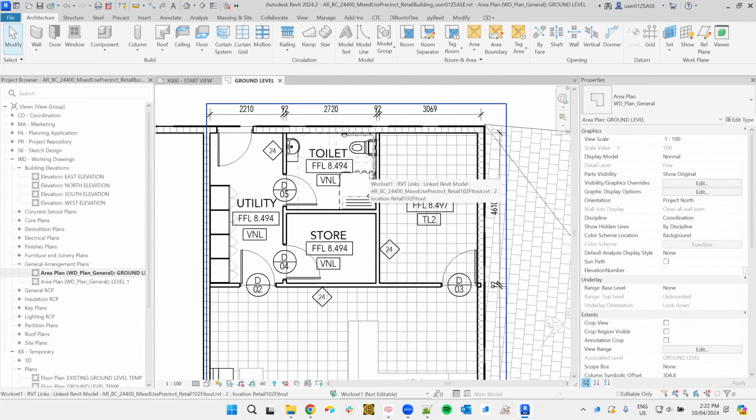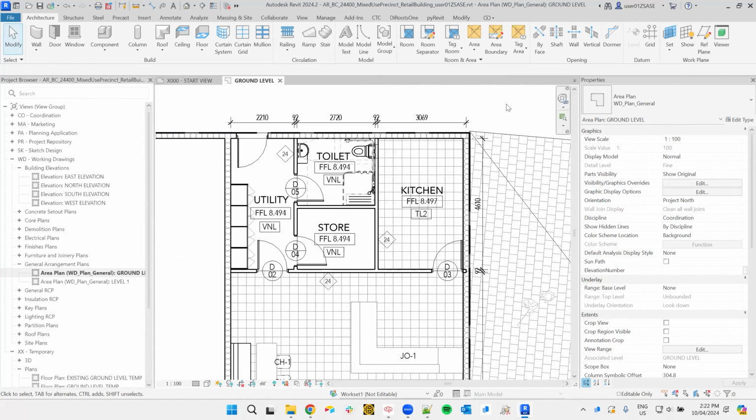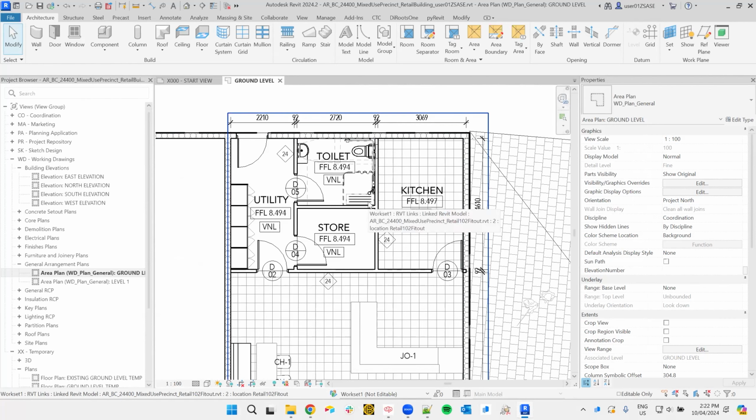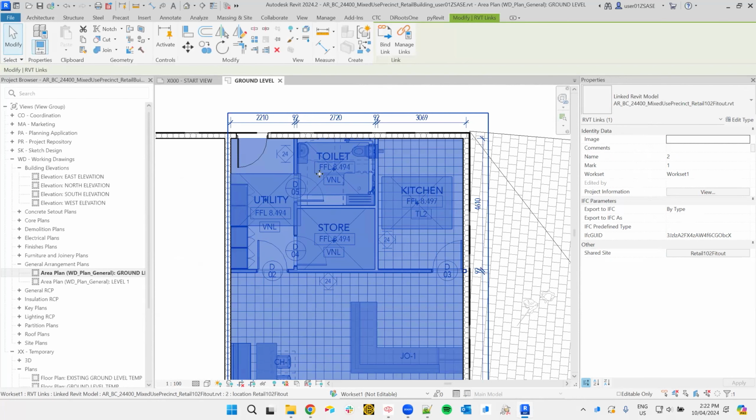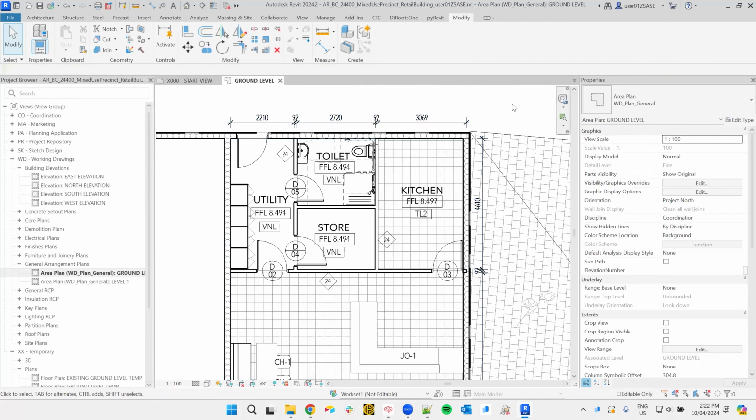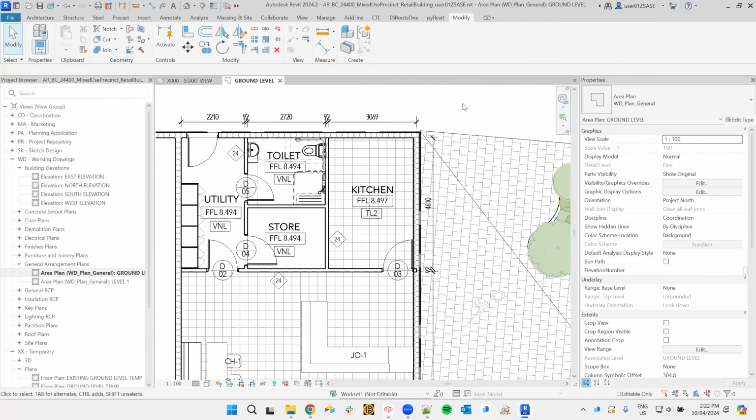Now, it's really important not to tag and dimension linked elements. We find that quite volatile. So our advice is to tag and dimension within the file natively, and that way you won't have issues where tags and links are dropping off.